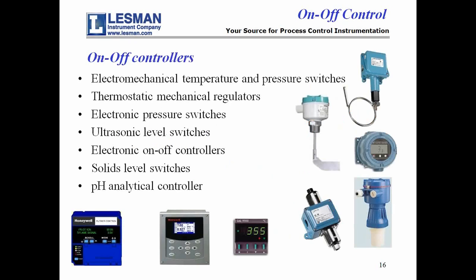On-off controllers come in all shapes and forms. You can see some are mechanical here. We've got the rotating paddle for level, the capillary and bulb for temperature, the bellows on this differential pressure switch, and then some of them are electronic. There's the safety controller that shuts down the fuel supply to a burner, a pH controller that's on-off for pH control, and a little temperature controller that's on-off.